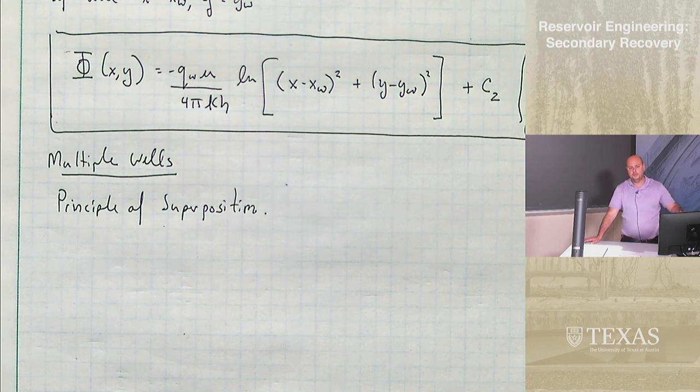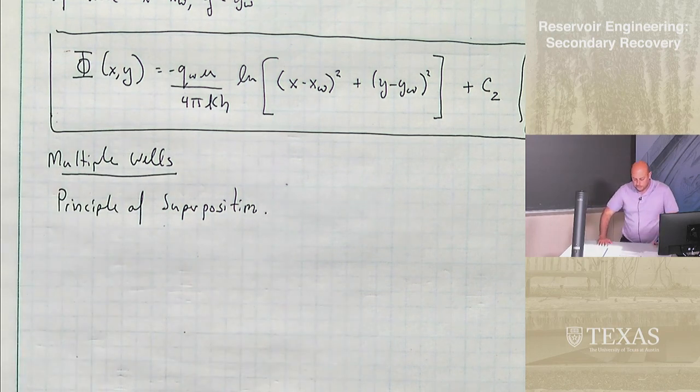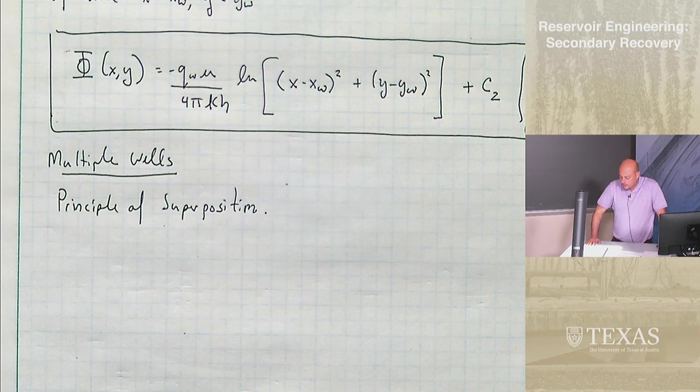Then we learned about superposition again when we were talking about aquifers earlier this semester. We learned about superposition when we were looking at the solution for a tracer when we just injected it for a period of time. Okay, and what we've learned over and over again is that there are some mathematical problems, specifically linear problems, and we won't get into the details about that, where if you've got multiple responses to something, like if you have multiple wells, then you can just directly add the solutions together.